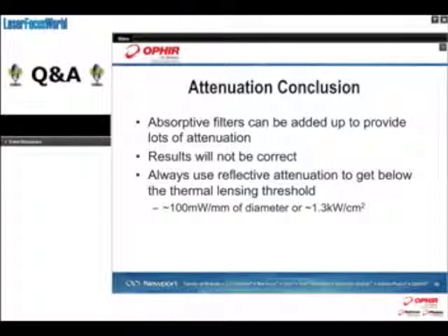Or actually, if you're going to use a scanning slit, you'd be well within the direct measurement level at that point. So with just two reflective surfaces, you could then probably measure that directly at focus with a scanning slit profiler.